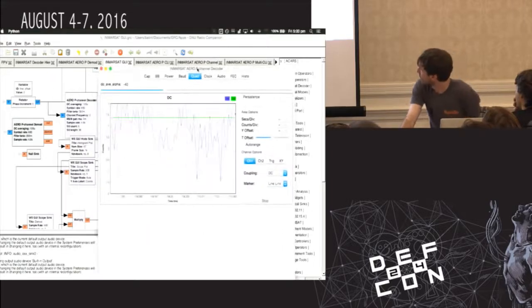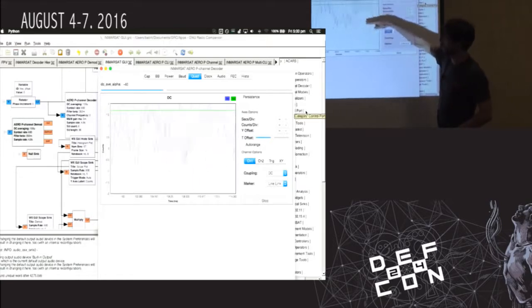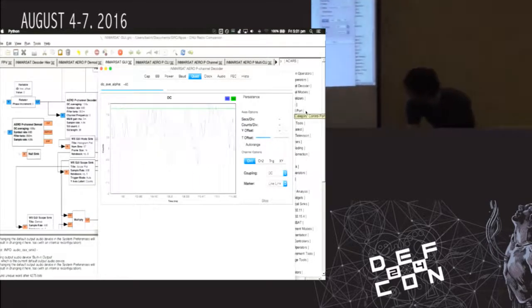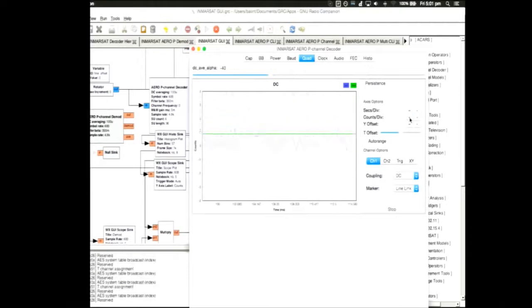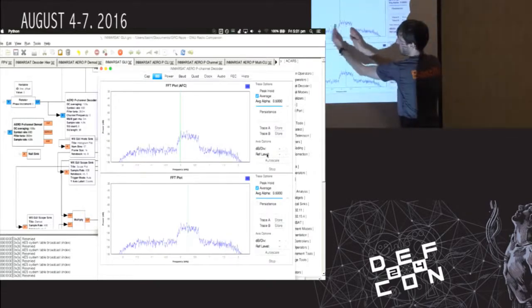Okay, there we go. What's interesting is this is the signal before the filtering step, so it actually looks really noisy, as you can see. But as it turns out, when you take the long-term running average of the filtered version of the signal, you see how the green is actually up here instead of at 0? That's because once you've done the quadrature demodulation, although it's worked, it's still within our bandwidth, it's just off-center.